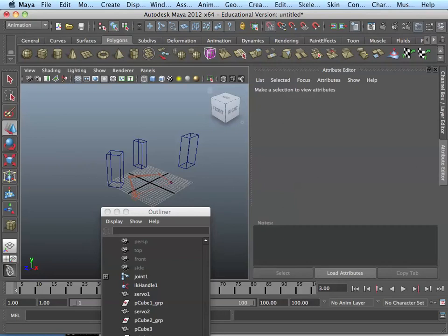Then in the hardware, I'll wire it up here in a second. If you remember, the control pin for the first servo went from 2. It just steps down the line, so the next one's at 3, the next one's at 4, 5, 6, 7, 8. But as I mentioned last time, you can get away with powering one of the little servos just off your USB. Anything above 1, and you'll start to get over-voltage warnings on your USB ports because it's just more power than that can supply.